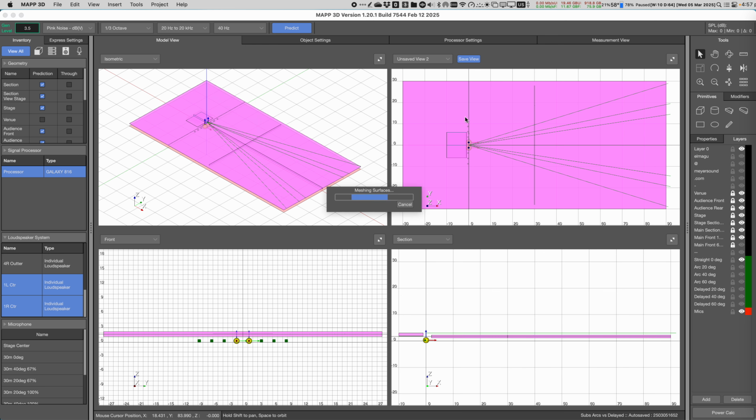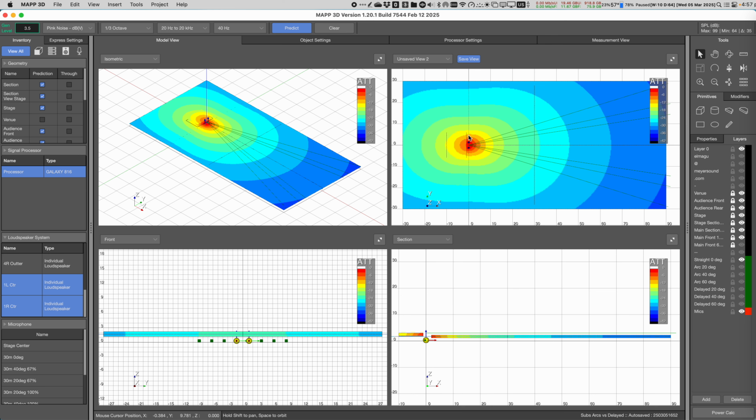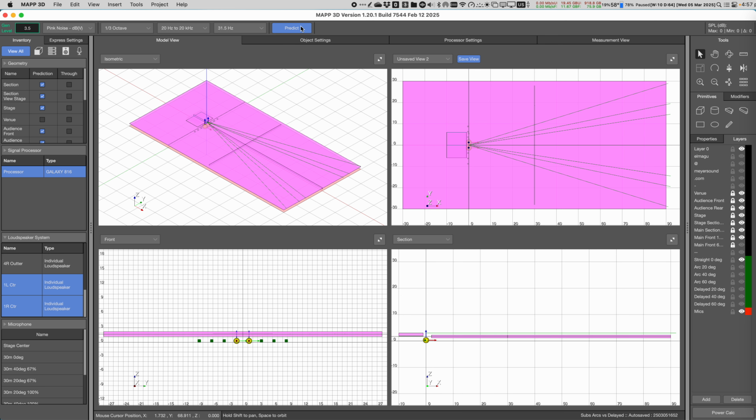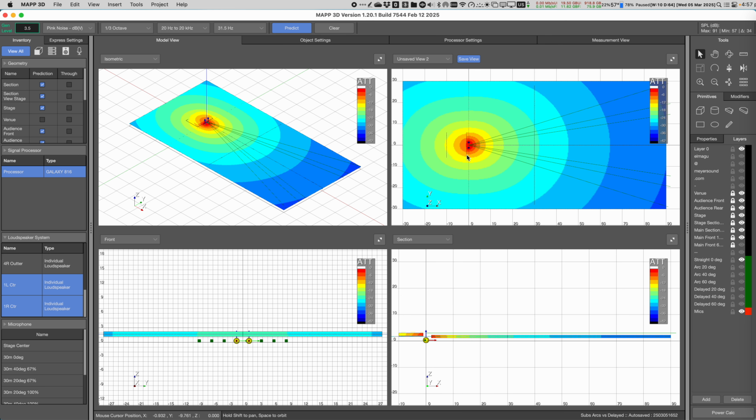And if I go lower in frequency, the level of the attenuation in the lateral decreases, and even lower in frequency, the level of the attenuation in the lateral decreases. It's very important to point out that in the front there is no difference if we are in the center. In the front, the distance is not affecting the phase relationship because the two speakers travel the same distance in the same time. What we are discussing is the lateral.